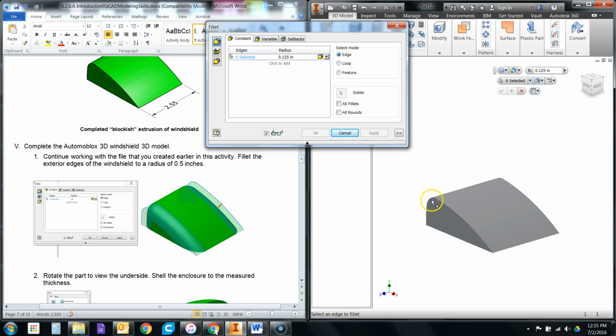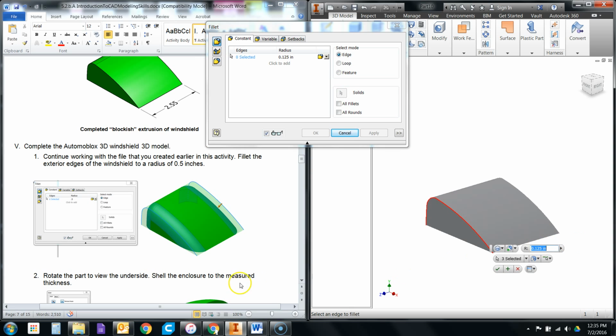It's where I've taken something that is two-dimensional, extruded it, and then now taking that edge that is set at a sharp angle and rounding it off as a round, or if it's an inside edge, rounding it off as a fillet. Now the tool is called fillet, but what I'm technically doing here is a round, and I want to apply a 0.5 fillet to it. Notice that this fillet is not nearly as large, but I've already selected it, so I simply need to change the radius of that fillet.